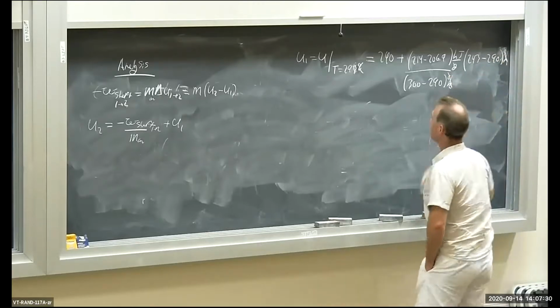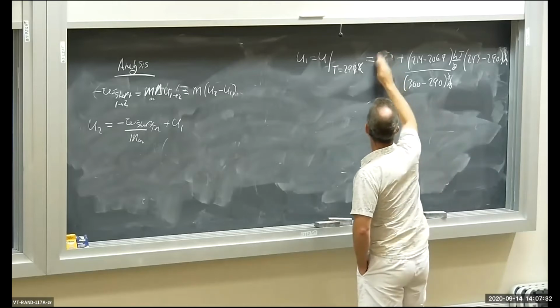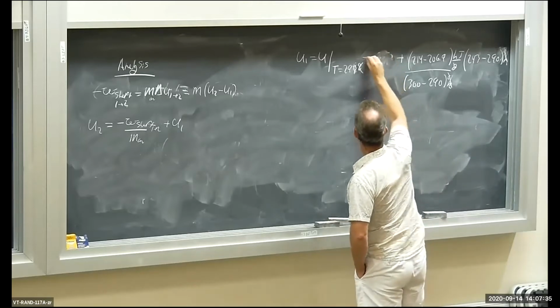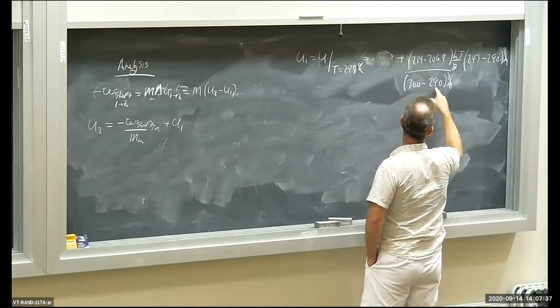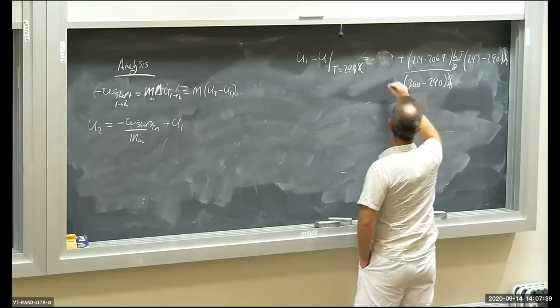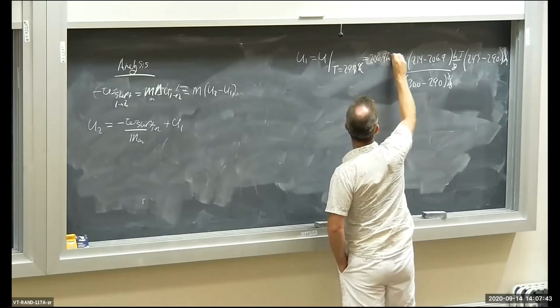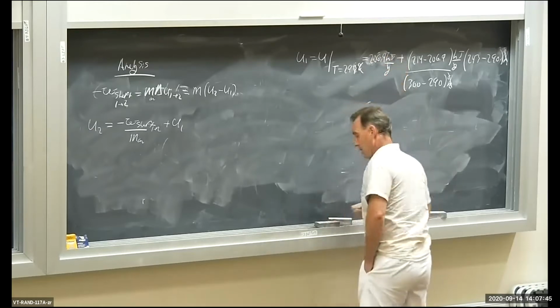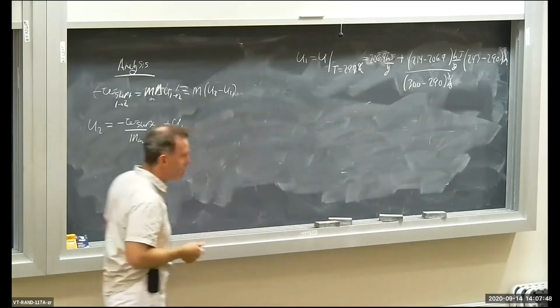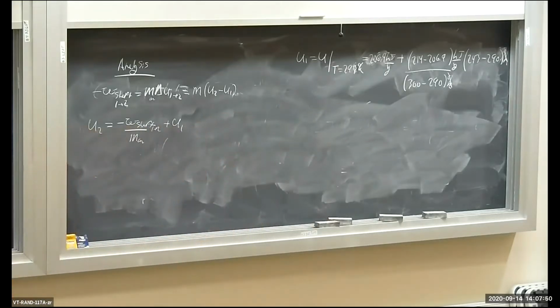The Kelvins cancel out. I need my base, 206.9 kilojoules per kilogram. I seem to be interpolating temperature, not internal energy. Okay, that should work.